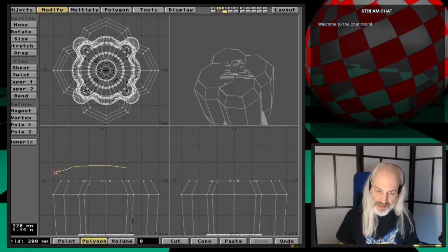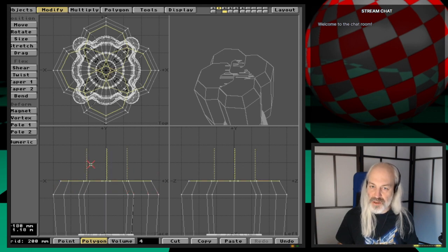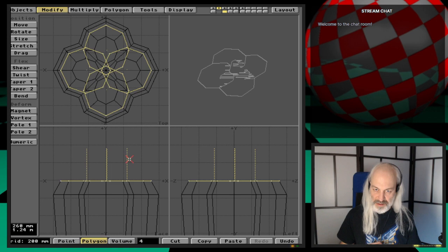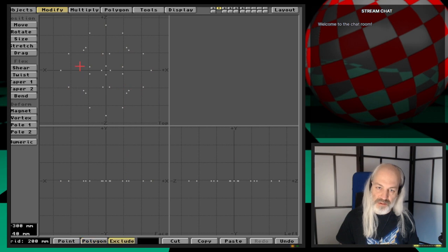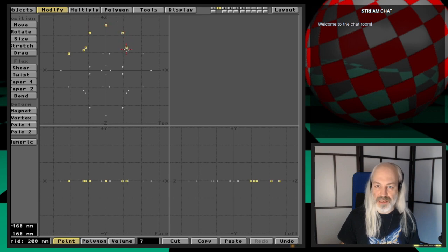You can fix these by first hiding all the other uninteresting polygons, and then you just kill these polygons and start drawing by selecting the outermost points, defining the silhouette of the final polygon.